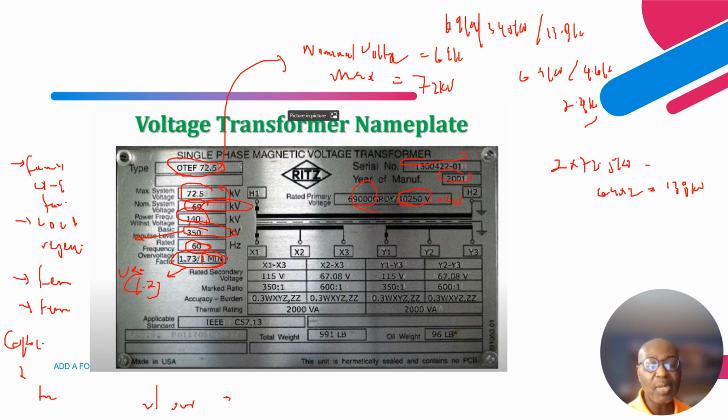Then let's take a look at the circuit on the primary side. Okay, so H1, H2, right? So polarity comes in. As you can see, this is the polarity, and this one is the ground, the top. On the low voltage side, you can see this is the polarity, right? So this one is a 2-core. It has 2 cores, the X and the Y, so X1, X2, X3, Y1, Y2, Y3.